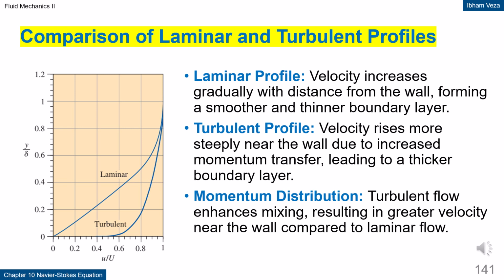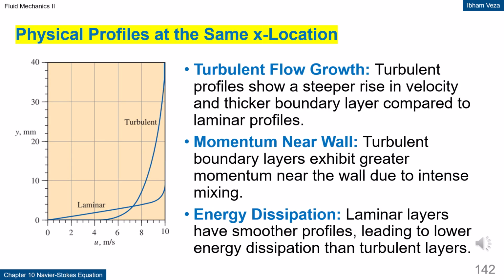At the same distance from the wall, turbulent flow has higher momentum. This difference is crucial in analyzing skin friction and momentum transfer. Physical profiles at the same x location. At the same x location, the turbulent profile is always thicker than the laminar profile.